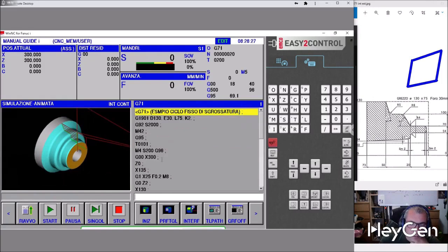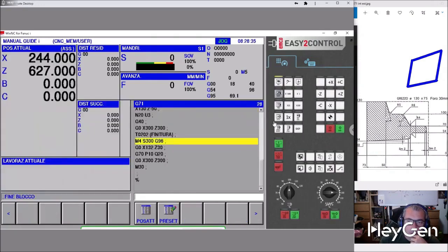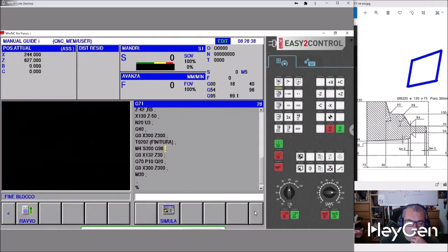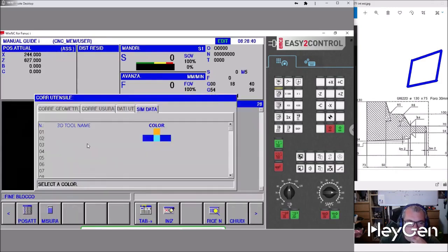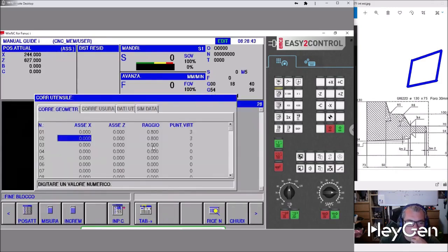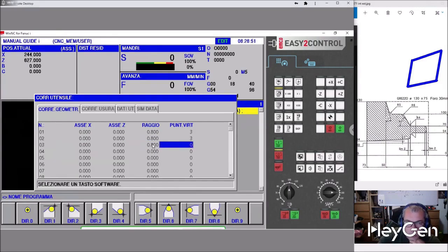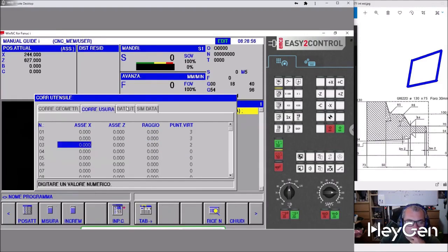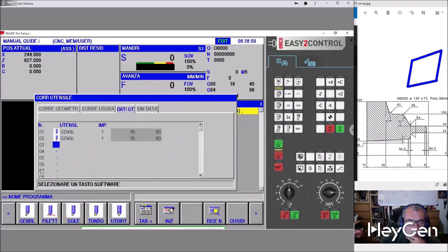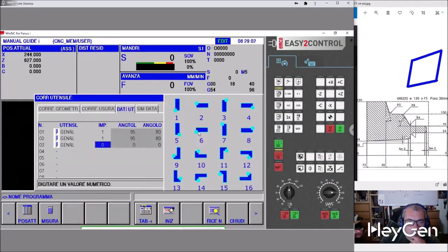Now we need to work on the inside, which requires careful and precise attention. What do we do first? Let's create a tool. So we'll take the T3 tool correction and proceed. We'll go into geometry T3 and say 0.8 as the virtual point tool radius, and here it changes. Here it becomes 2 because it is a boring tool wear corrector. That does not interest us at this moment, but it is positioned according to the drawing. 2.